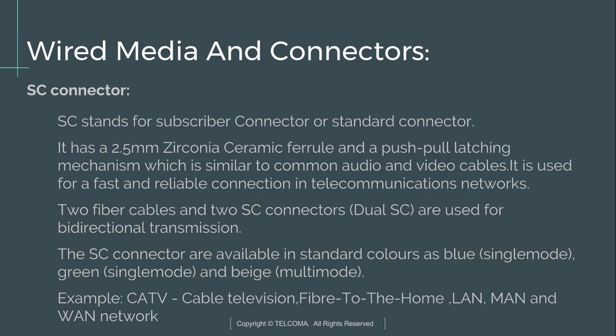So then is optical connector, the connector used in the optical fibers. So first is SC connector. SC stands for subscriber connector or the standard connector. It has the 2.5 mm zirconia ceramic ferrule and a push-pull latching mechanism, which is similar to common audio and video cables. So it is used for a fast and reliable connection in the telecommunication network.